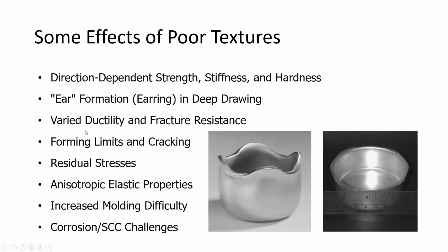Ductility, fracture toughness, forming limits, residual stresses certainly are directional dependent. Elastic properties, which if you think of elastic properties and what the elastic modulus or that lattice phonon controls, it also is related to conductivity, right? So if we have difference in elastic moduli, then we have different conductivity along those directions as well.